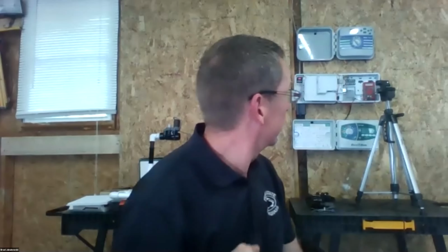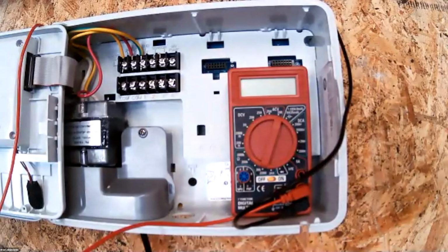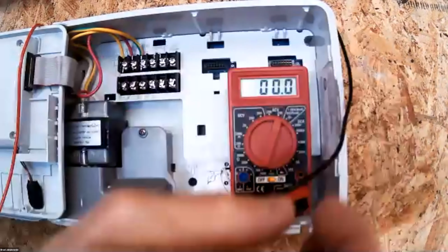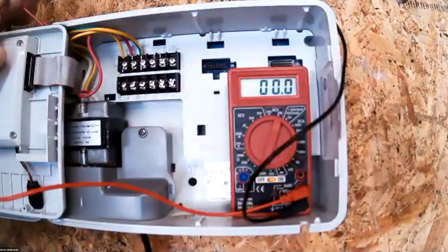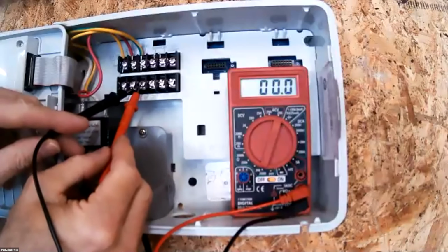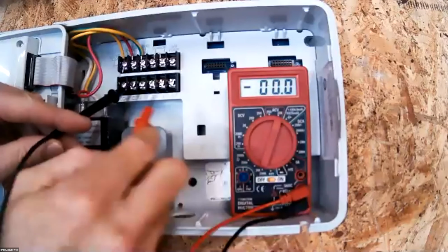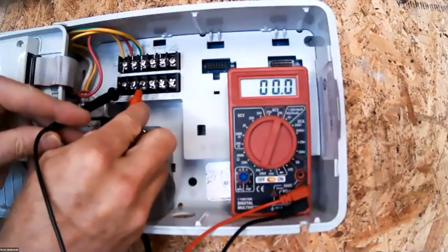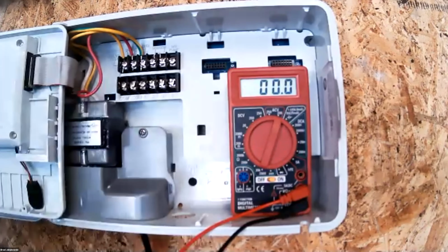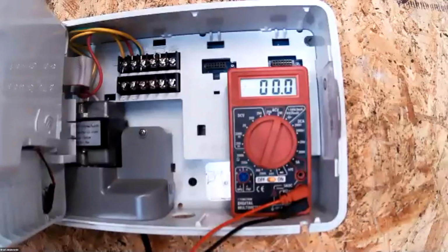And I'll see if I can pop that up real quick. See if this camera is working. Ah, it is. Okay. So for example, when you want to check power in, power out, with this one here, it may be a matter of just checking, okay, I've got station 1 right here. Do I have 27 volts AC? No, I don't. Well, you may also want to make sure you have the power turned on at the controller itself and see if that makes a difference.